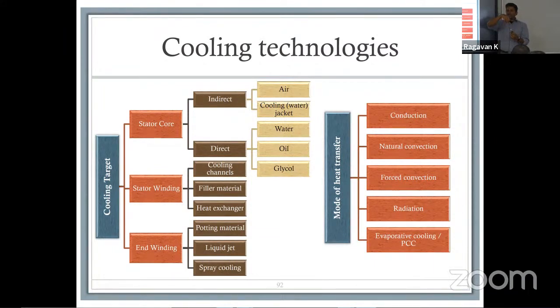When you insert the cell into it, the heat is transferred onto this wax. Graphite has high conducting properties. It transfers the heat onto the wax. That wax starts to melt. But because you've created a microchannel, surface tension stops it from collapsing, much like a candle. It doesn't collapse down. Once the entire wax is melted, you have a problem. But until that point, it can absorb the heat and avoid a catastrophic failure. Once the heat is gone, let's say it was a peak power draw of 30 seconds or whatever it is, the peak power is gone, it can recongeal, become wax again.